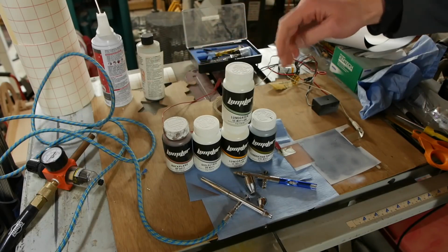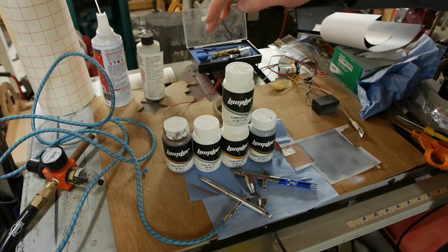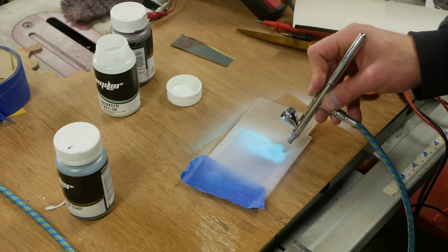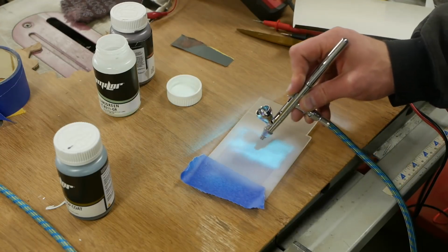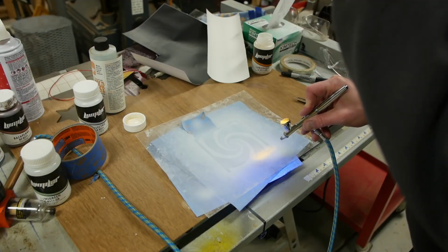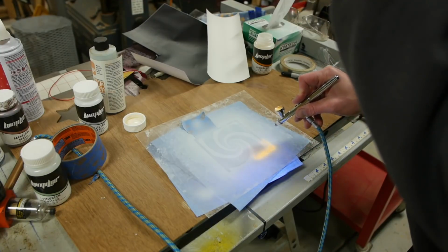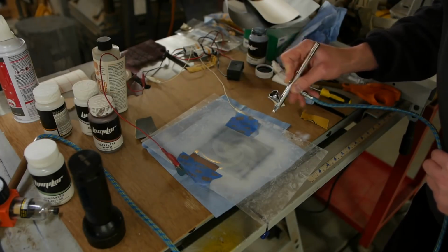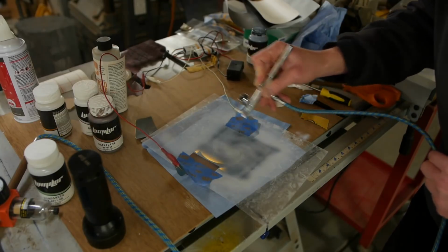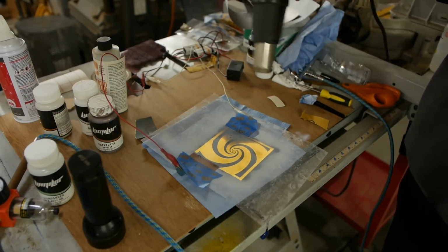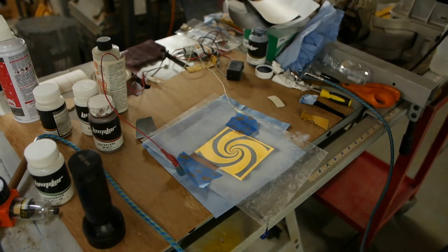You have to watch Ben's video for the full story, but in quick summary, electroluminescent displays are made by spraying a special luminescent paint over a piece of plastic or glass with a transparent electrode, putting a thin layer of insulating dielectric, then forming another contact on the other side. When a high AC voltage of say 300 volts is applied between the two electrodes, an eerie glow is produced.